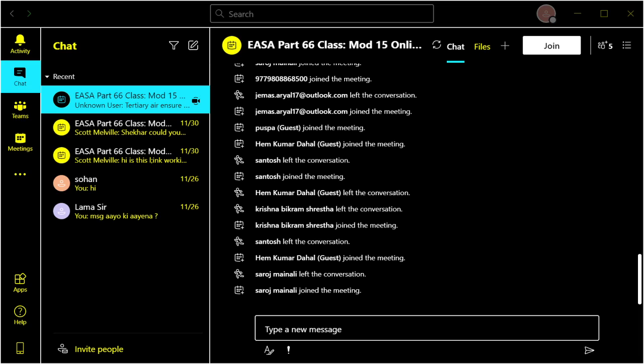So this fuzz burner, as the debris builds up, it's metallic obviously. Once it hits the sides, once a certain amount is on the magnet, it makes a circuit, gives a warning to the cockpit, and what can happen, it might just be, it's maybe had heavy flying, it's maybe a lot of debris flowing about, it's not actually too bad. The pilot can press a button and actually burn it away, hence it's called a fuzz burner. So it actually burns the debris away.